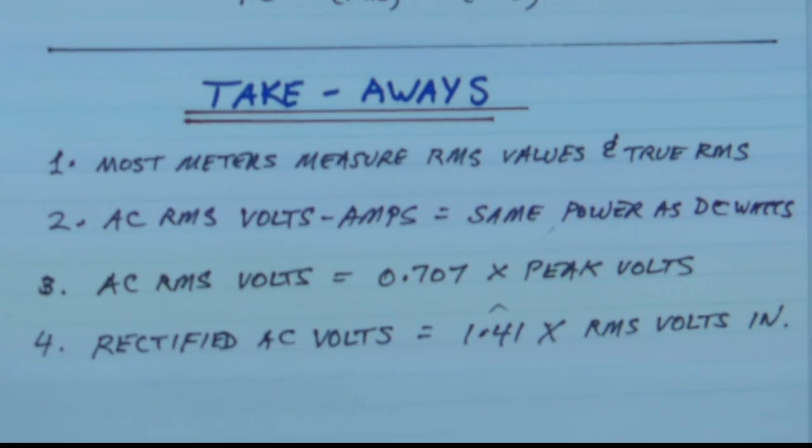There's a different way of calculating the averages for those, and certain meters will do it for you, will automatically set up the circuit so that it calculates the output in true RMS. So it'll give you the equivalent RMS voltage in terms of that particular waveform. So that's why true RMS measurements are sometimes important.